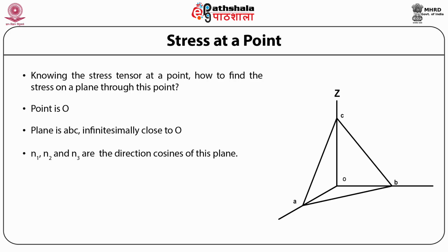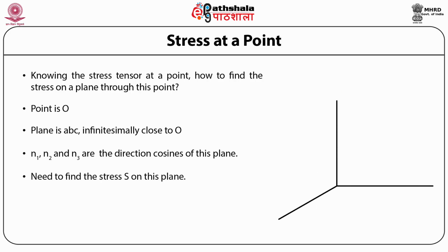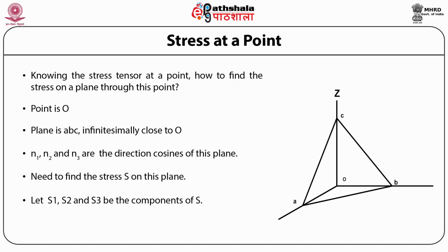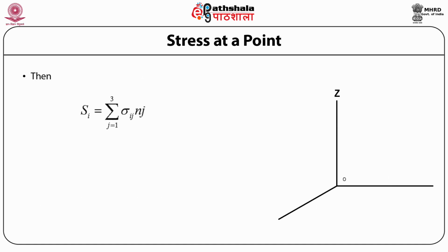Then it can be shown easily that the components of the stress on this plane are S1, S2 and S3, where Si equals the summation over j equal to 1 to 3 of sigma ij times Nj.